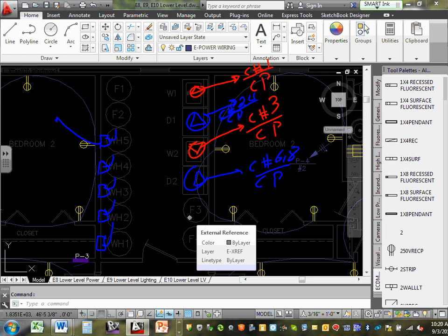And then we need to have a circuit. Each one of these circuits will have a neutral, a hot, and a hot, and a neutral and a ground. That's how the circuit for it is going to look. This is water heater number 5, so it's going to be apartment, say, 2 and 4 from the common panel, or panel 5. We called it panel 5, didn't we? I think we called it panel 5 at the end. So this is going to be P5.